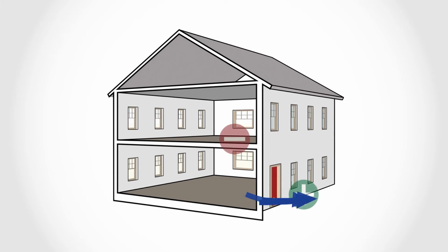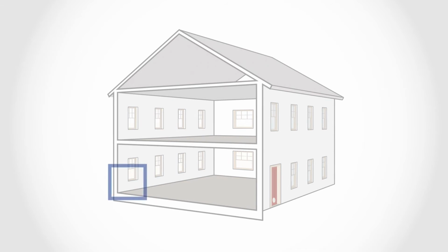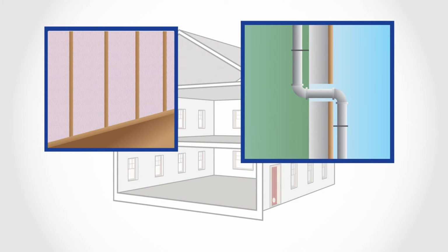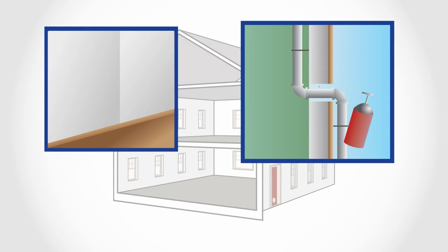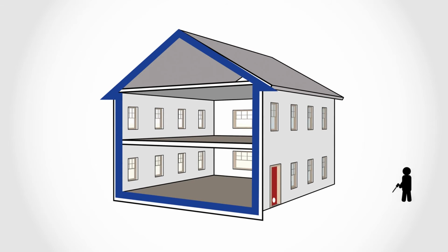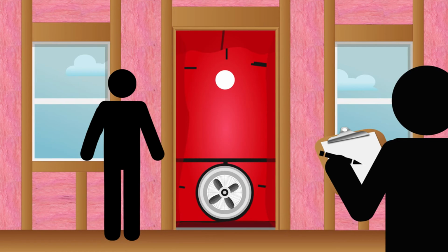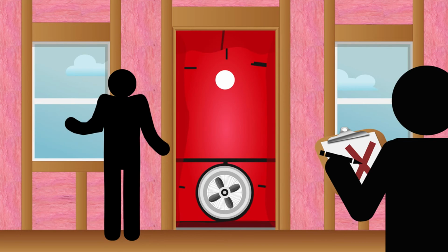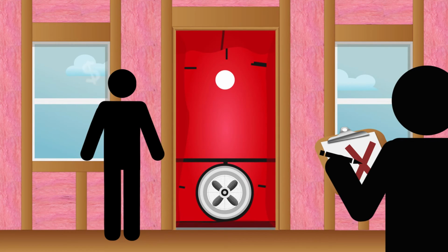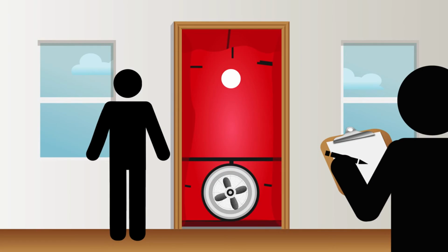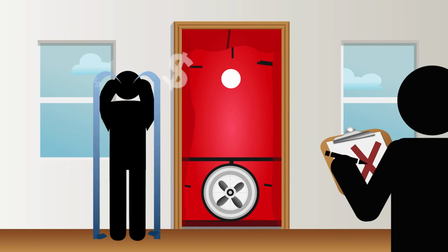The blower door test used to comply with the law must be performed when the structure is complete, including all drywall installed and all penetrations properly sealed. All HVAC systems must also be installed, and all subcontractors should have completed their work, so no further inadvertent penetrations are made. It is good practice to perform preliminary blower door tests during construction to make sure the project is on track to pass the final blower door test and to avoid costly delays. It is cheaper and easier to repair air leaks before the drywall is completed.